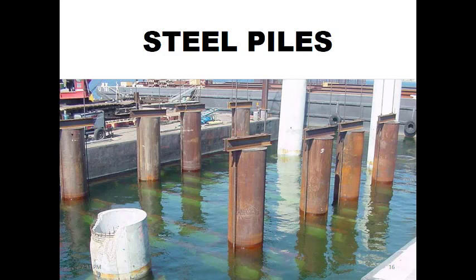But when you reach anything solid compared to the wood, compared to the material that can accept the nail itself, then you will realize the resistance of that particular material when you are hitting the nail. Let's say you are putting a piece of wood on concrete and then you are trying to nail it. Once the nail passes the thickness of the wood and reaches the concrete, you will feel the resistance when you are hitting the nail. So it wouldn't drive any further, but it will shoot back.